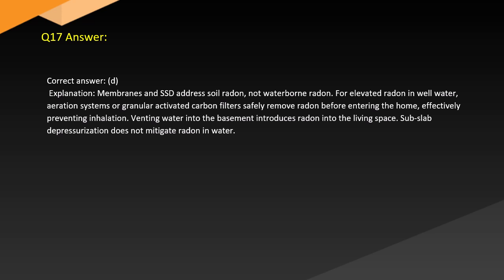Answer. Correct answer, D. Explanation. Membranes and SSD address soil radon, not waterborne radon. For elevated radon in well water, aeration systems or granular activated carbon filters safely remove radon before entering the home, effectively preventing inhalation. Venting water into the basement introduces radon into the living space. Sub-slab depressurization does not mitigate radon in water.